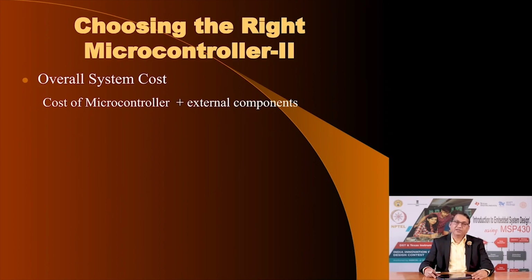Now, you see in this light, if one were to choose the PSOC microcontroller which has programmable analog components on chip, it would reduce the cost, and it would do further that it would also reduce the cost of the PCB. So, the cost of a PCB is an important consideration in the overall system cost. Having less number of components, because you choose a microcontroller which has higher integration of the requirements that you need, would lead to smaller chip count. It would also increase the reliability of your product, and it will lead to a reduced cost of printed circuit board, thereby giving you a more economical product. Therefore, it can be more competitive.